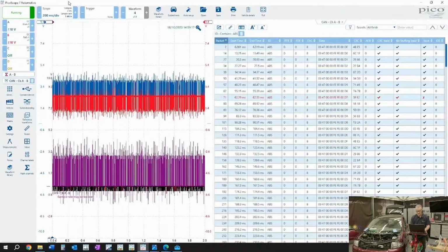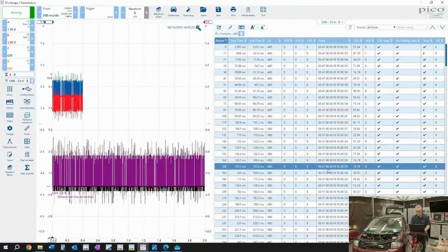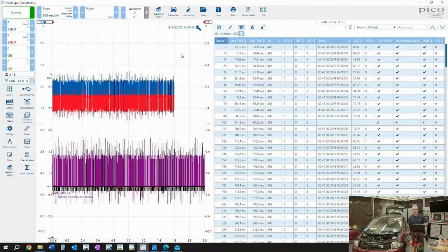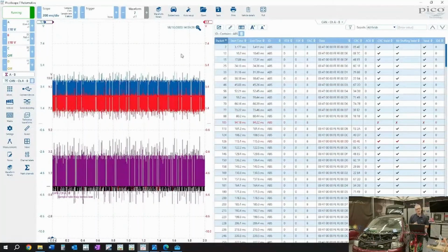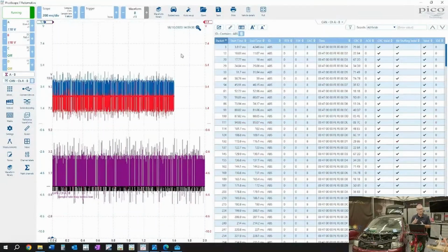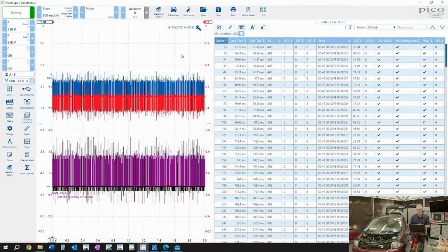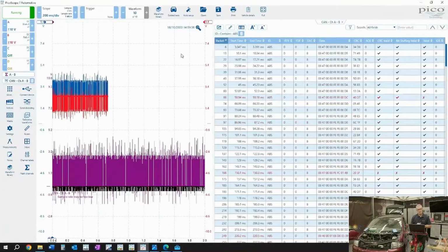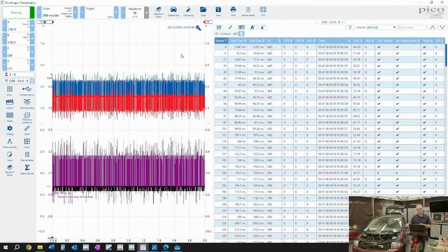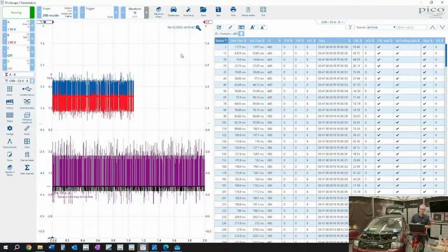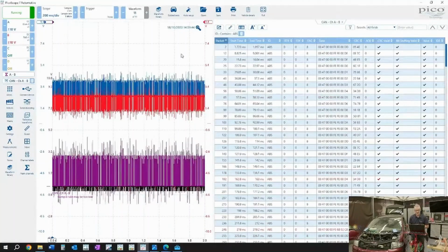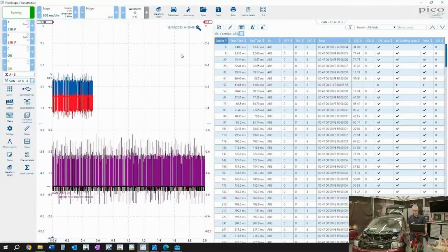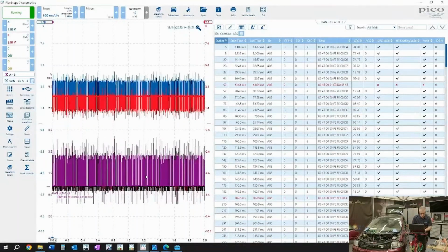Now, just note that in the data field, we have 0047, and it's that second byte that I wanted you to keep an eye on, because the plan is now to actually press the brake pedal, because I know either through reverse engineering or DBC that byte 2, by changing one digit, represents brake pedal position on or off. So the plan here, and I've enjoyed doing this actually, was to operate the brake pedal, which is a physical connection. In fact, I've got the wiring diagram here.